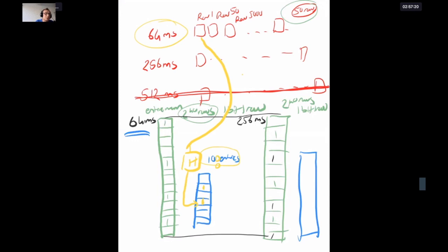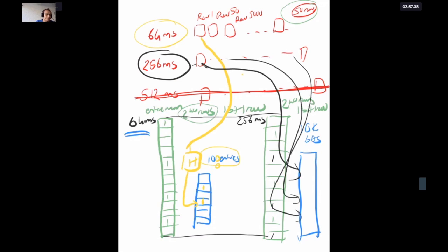Basically, have a larger Bloom filter, let's say 10K bits, and insert into that Bloom filter the rows that essentially need to be refreshed every 250 milliseconds, right? You basically take everything over here one by one and set the right bits over here. And in the end, you have a Bloom filter that has the right bits set that are associated with the row addresses that need to be refreshed every 250 milliseconds.